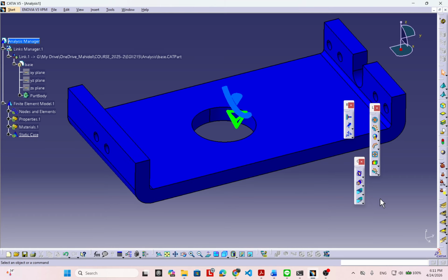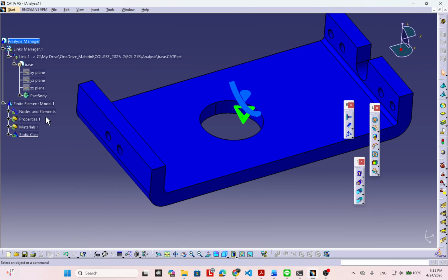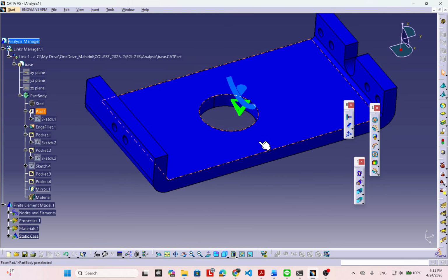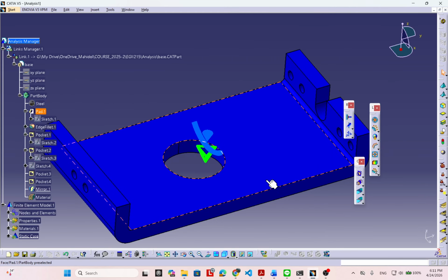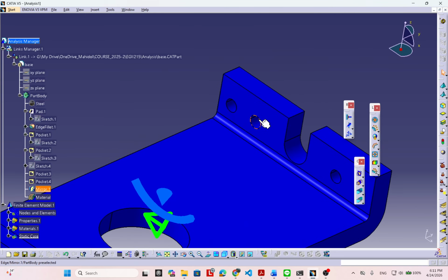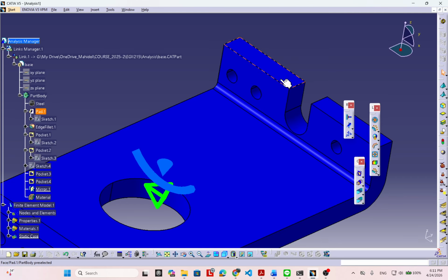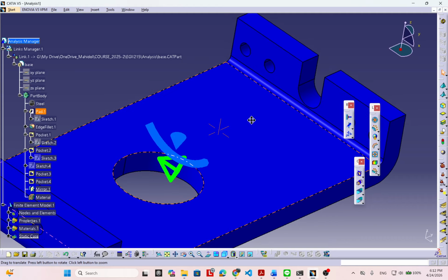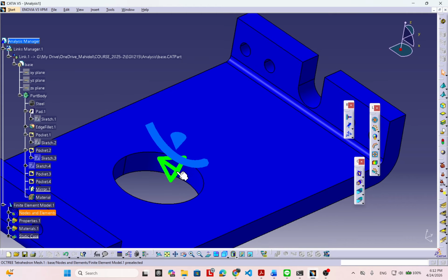Okay, I should try it like this. If I use it, maybe it's very big, right? Okay, this one is a big solid mesh. Let me see, yeah, the small hole maybe it's not good, right? And this one is not matching about here. Maybe the hole is not a circle anymore because this one is bigger, it cannot represent the structure around the circular hole. It cannot represent the edge. The edges at all should match the solid mesh, right?